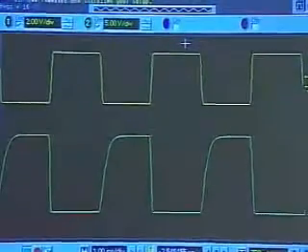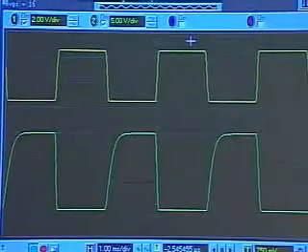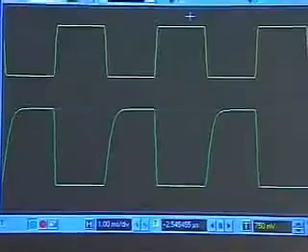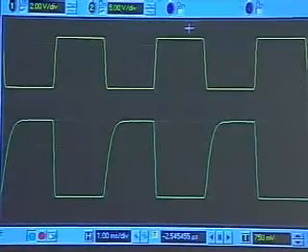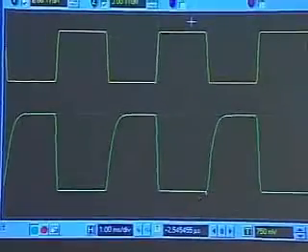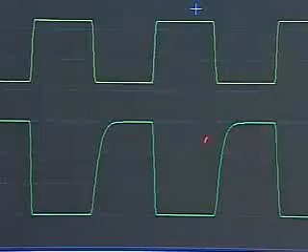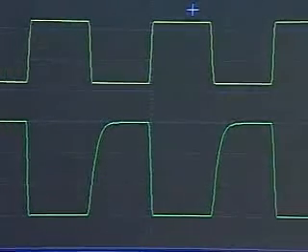I'm going to show you a few numbers, so hang on for 2 minutes after this demo. I'll give you some numbers, and I want you to go ahead and compute the numbers based on what we've seen here. And you will get suitably impressed, I promise you. So this is the input fed to the inverter. This is the output of the inverter. Notice that the output of the inverter reflects some sort of an RC time constant because of the output driving the capacitor.